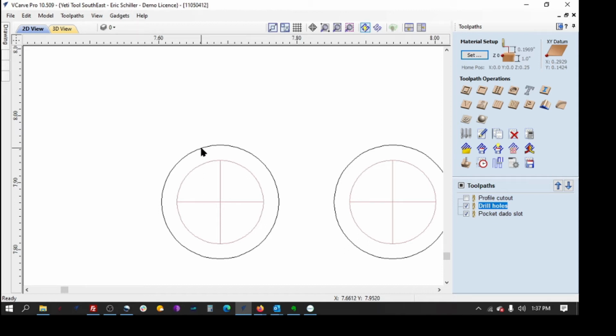So again, there are different ways to do it. I can pocket all the way through it, or I can have the proper size drill bit and go down in one punch, or do the Pec drilling and things like that. So this little bit was just added into the video because I saw my error. I had said it was 0.13 using a 0.125 bit, and it's 0.17, and I had selected a 0.125 bit. Bit selection is important, but let's move on.